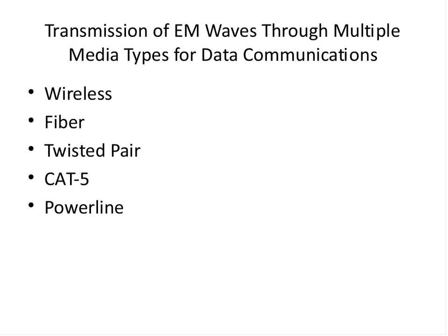It's actually for digital communication, and it's used for Ethernet, IEEE 802.3. I believe we use 4 wires, but it has the capacity for 8. 4 pairs. Yes, 4 twisted pairs. But not all the services are used. Most often, all pairs aren't used. So the point was validated that not all the pairs are used, but this is a good way of carrying digital information.